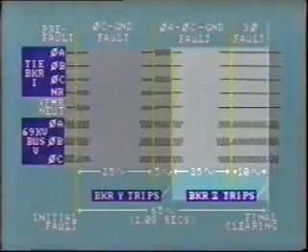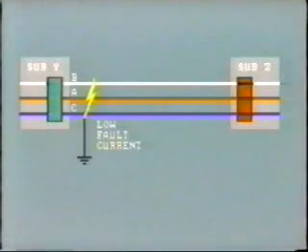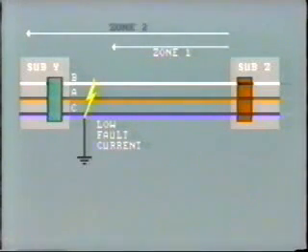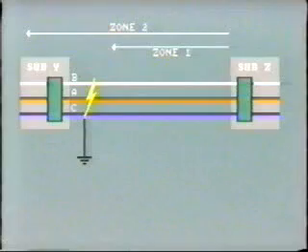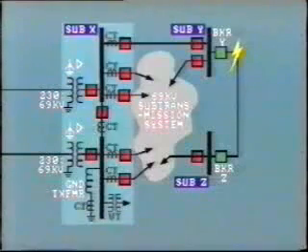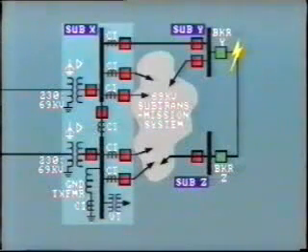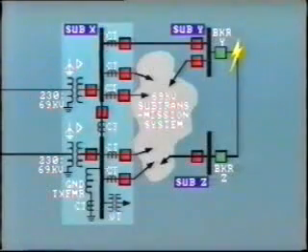This occurs 35 cycles after breaker Y trips. Again, this is reasonable because the fault current is low and also because the fault is in zone 2 of breaker Z's protection. Thus, tripping is further delayed. This example has demonstrated two things. First, the nature of a fault can change during a disturbance, and in this case, the protection operated correctly to clear the fault. Secondly, our example showed that recording equipment located several buses away from the actual fault can still provide valuable information during a fault investigation.